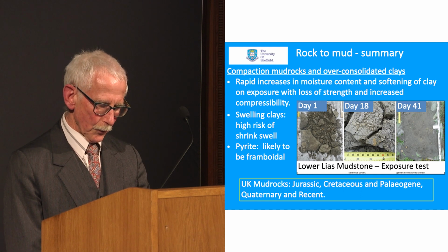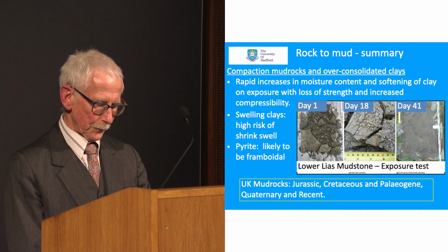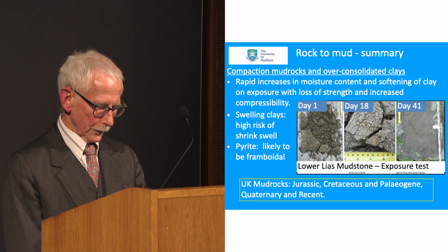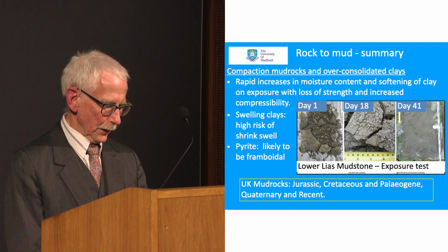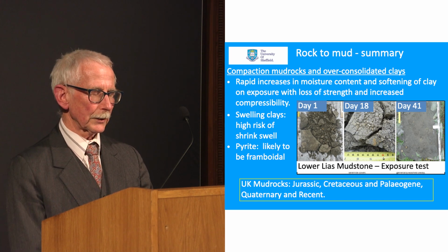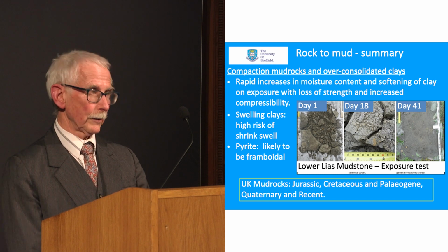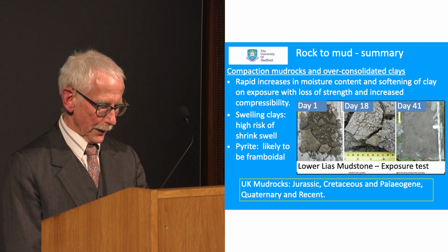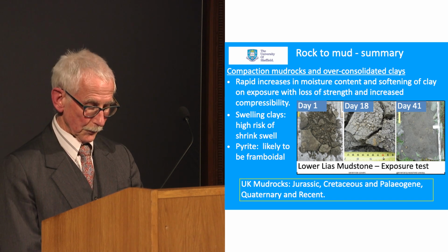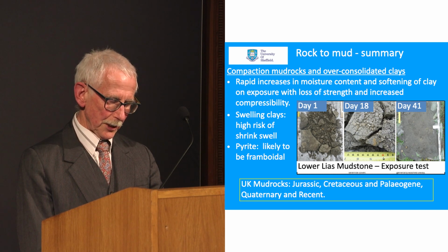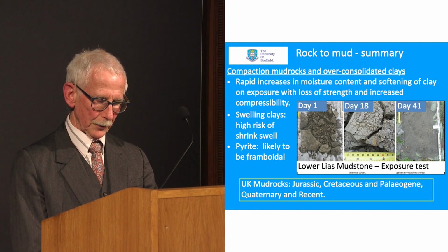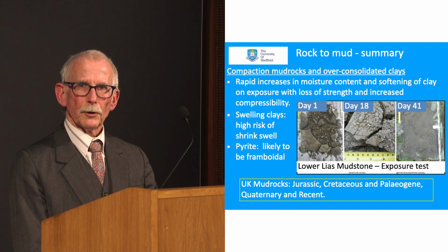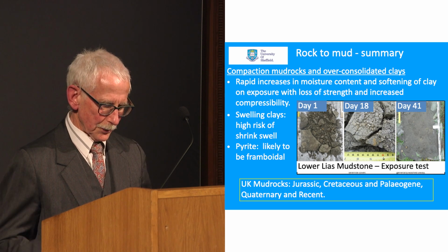And exposure to air and water will cause the material to degrade rapidly, causing the clay to soften greatly and the pyrite to become oxidized, producing high sulfate acid conditions, and more about this later as well. But by rapid, I mean changes are liable to occur within the construction period. Complete breakdown of this Liassic age mud rock from near Nottingham occurred in 6 weeks.